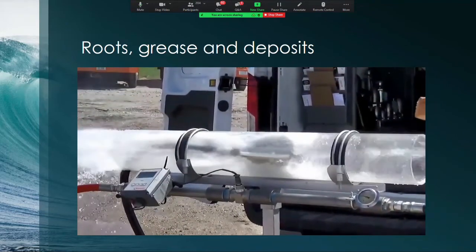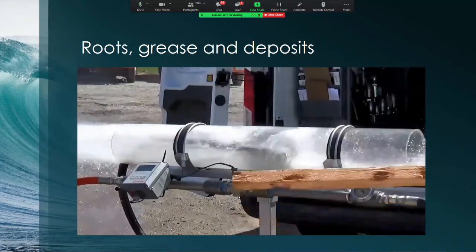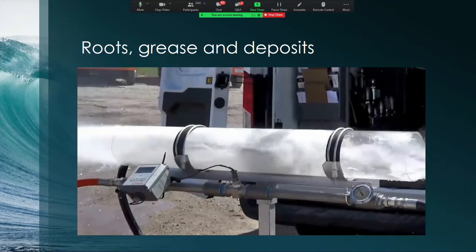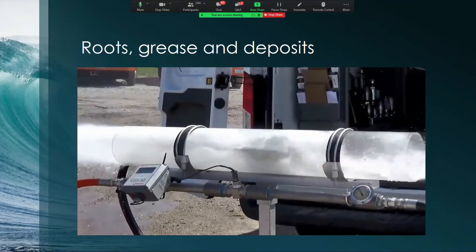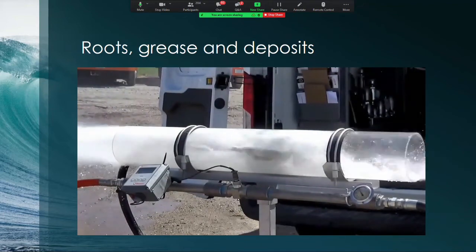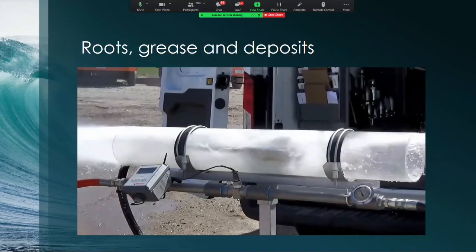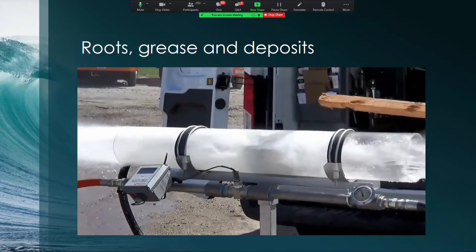Again, remember, controlled rotation head. This nozzle turns at 600 RPM, regardless of the pressure you put behind it. We use a centrifugal clutch inside and a braking system inside the nozzle that basically requires zero maintenance. There's no oil changes or anything else to do to this thing, other than wiping down the nozzle when you're finished and making sure the water jets are unobstructed. There's no maintenance on this nozzle.